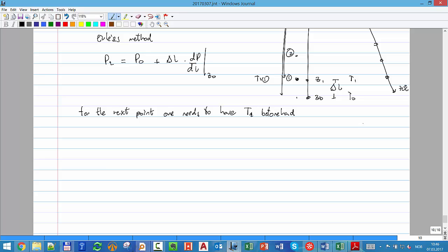Another way that is more complicated is if a temperature drop model is available. Okay, you have, for example, a function, temperature as a function of depth. You can use also that. The thing is that you have to have the temperature at every point, and repeat. That clear? So you see, it's a lot of work.